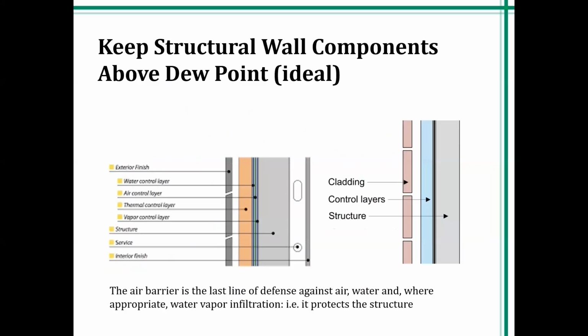Again, whenever we have moisture sensitive materials, obviously I mentioned gypsum, but steel framing is not immune. I have an image of steel studs that were completely rusted out. The whole vertical faces were just rusted. And you can only throw so much galvanization at the framing. So again, you really want to protect those moisture sensitive materials.